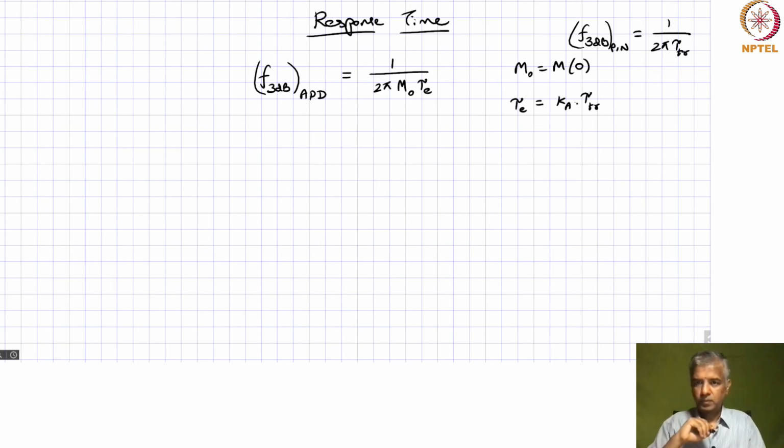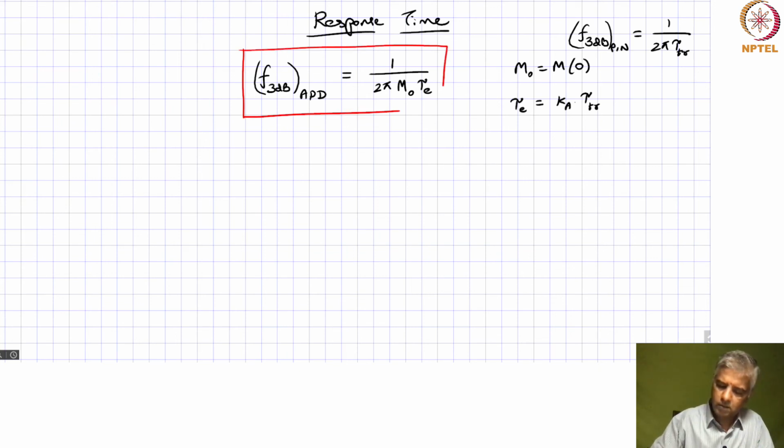So Ka, like we said, can be a value of 0.5 for indium gallium arsenide, 0.1 for silicon, and correspondingly the gain value could be in the order of 10 for indium gallium arsenide, and in the order of 100 for silicon. But this is the trade-off now.